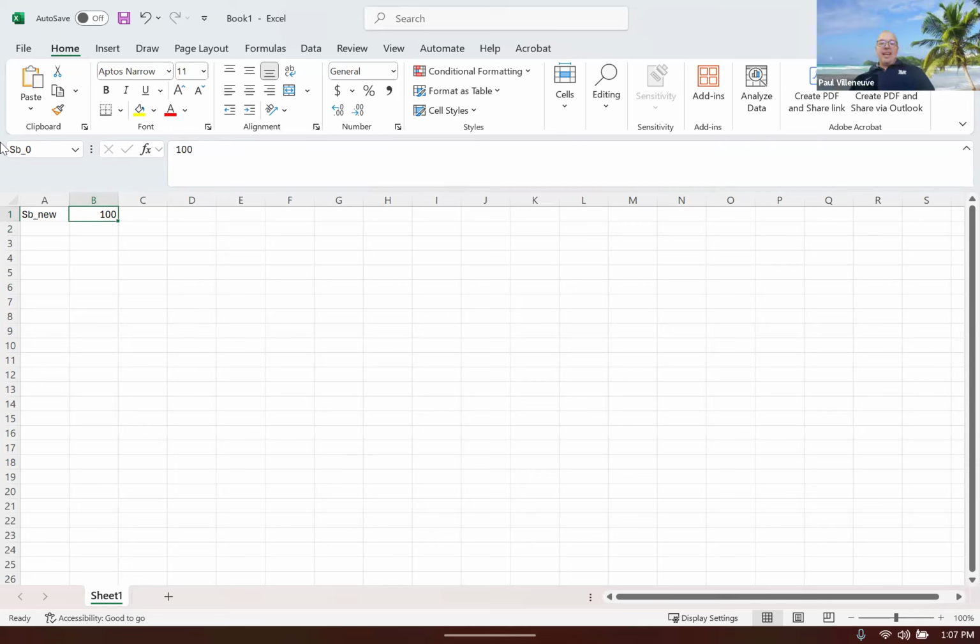All right. Now I'm going to go into my VBs. So VB in region 1, we said was 22 kV. And I'm just going to put everything in MVA and kV. The reason I do that is because when you do VB squared divided by S base, kV squared is mega, divided by mega, so the units will cancel out.